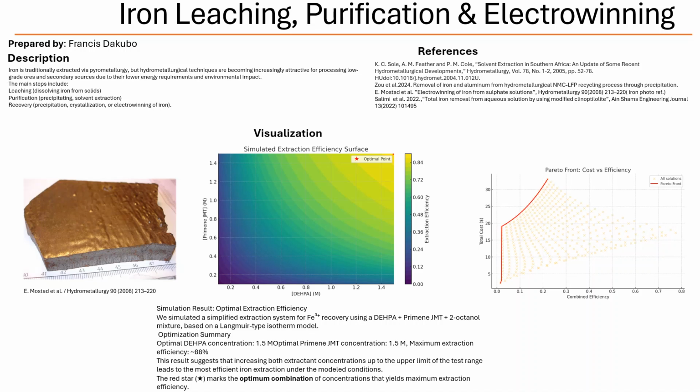Pure lead wasn't quite strong enough, so they developed a special alloy with antimony and tin. It had a very low corrosion rate, something like 0.13 to 0.25 millimeters per year, which means the anodes could last for several years. They even designed the anode with a sawtooth edge. Why was that? It seems to help with the current distribution and the release of gas bubbles, making the process more efficient. They also welded it to a copper bus bar for better electrical contact. Okay, so they put a lot of thought into the anode design.